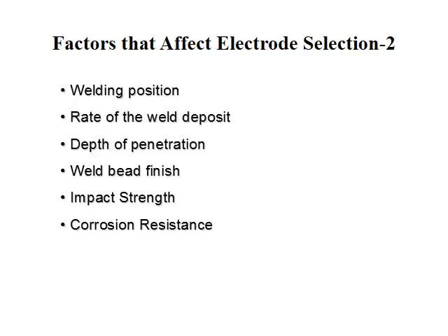Corrosion resistance. If you're making a weld on some corrosion resistant steels, you probably want a weld material that's going to match up with the corrosion resistance of the base metal.